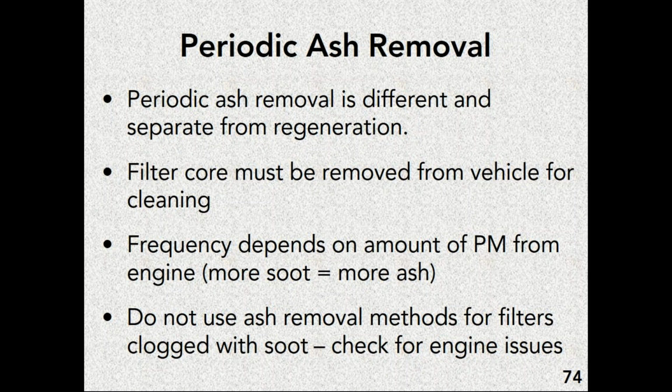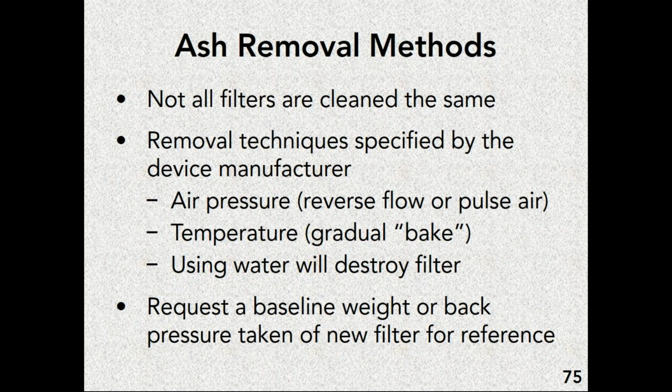Not all filters are cleaned the same way. Some of them use air pressure, some of them use temperature, some of them use water. I know it says water will destroy a filter, but I just recently looked at a device that uses saponification, which is soapy water, to clean filters. That and sound waves to actually get the ash out, collect it, then they super dry it and make sure that the filter is operational again. These are all methods to clean the filters.